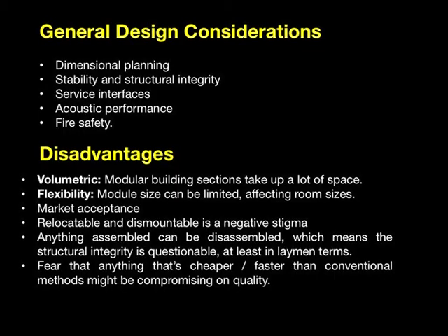All the service conduits, all the fire safety measures, even the size of the fenestration, windows, doors, size of openings, size of ducts, cutouts, everything needs to be pre-engineered and predetermined, and only then we can start the construction, and only then the construction will go smooth. The grid planning, and it needs to be designed for transportation. There is a very big disadvantage in this modular construction because during transportation anything could happen. The modules that you are going to design need to be transported from the off-site factory facility to your site, which means it needs to be transport friendly.